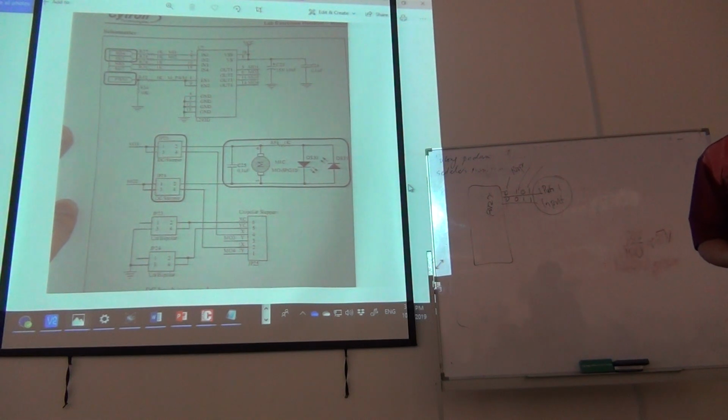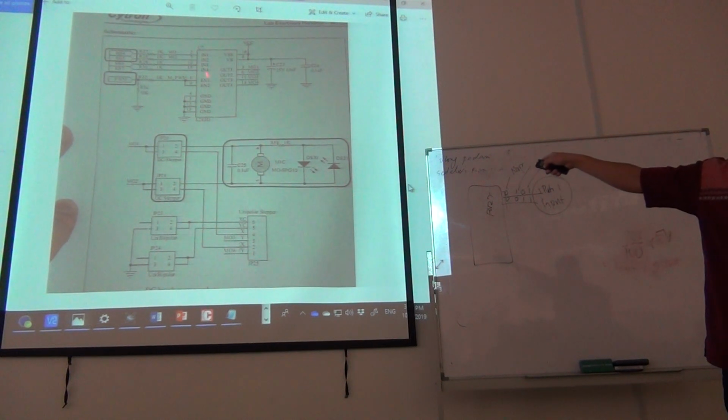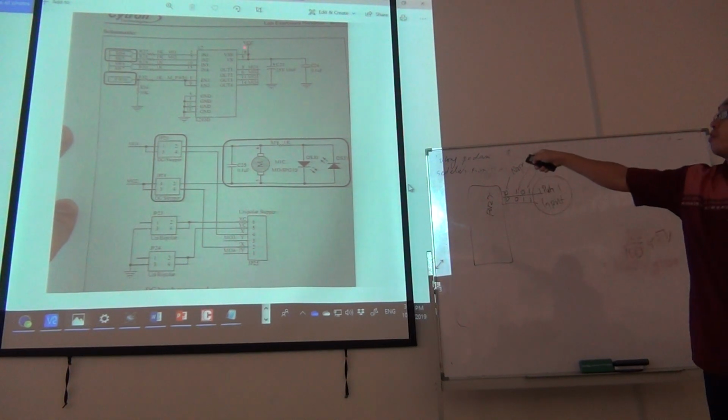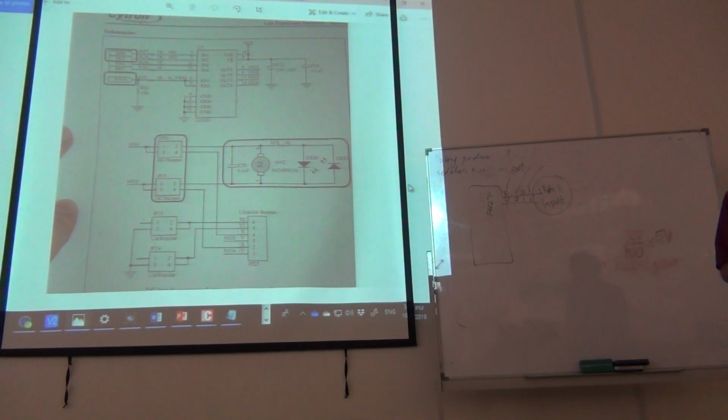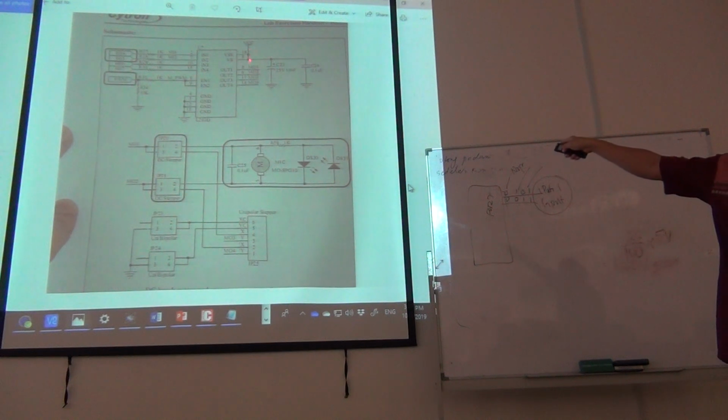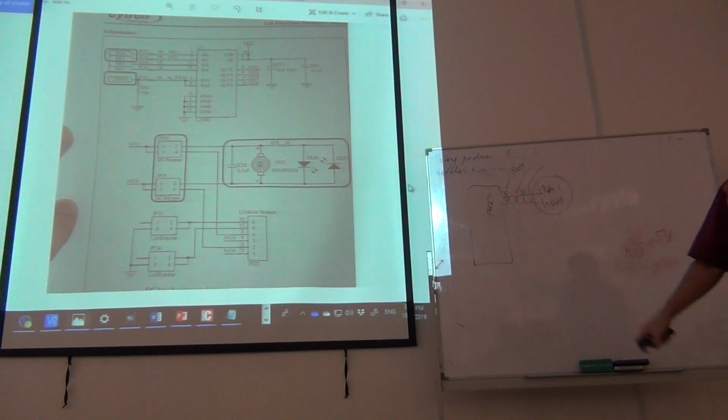Anyway, it can operate with different voltages like 12 volts and 24. But on the board now, it seems like it is sharing the same node. So VSS powers up your L293D at 5 volts, and it's also shared with VS, which means that the power for the motor is also 5 volts.